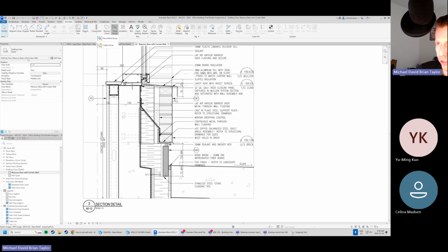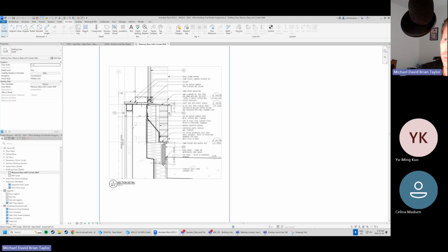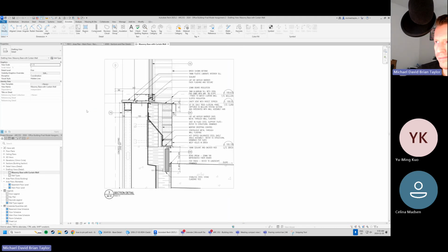So where do we want to start, right? Where do we want to start? What we might start with is the grids. It's usually my favorite place to start, just so we have an understanding of about where the drawing might be taking place. If it's a completely irrelevant drawing, you might not need to use the grids themselves. So again, these grids that you're going to be drawing are not tied to any piece of your model. So be very careful when we're drawing grids here.